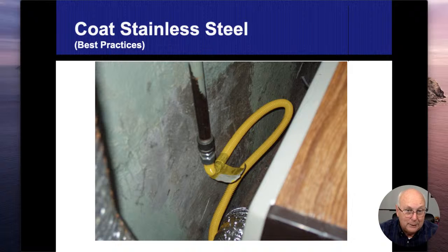So we're supposed to have these things bonded, and typically on both ends of them, because they're not strong enough to conduct the electricity. So we need to give that electricity a pathway someplace else to get to the water pipes, and then get it out of the house.